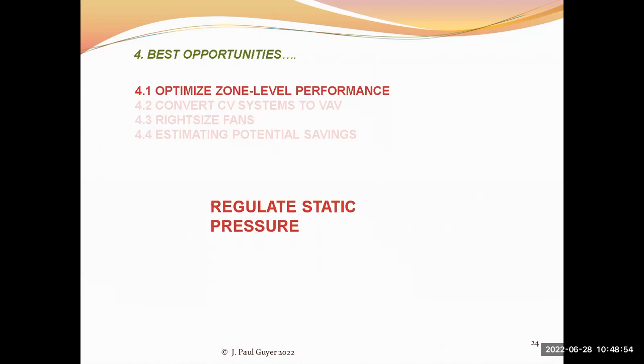In other words, are you forcing air with the fan into the ductwork system at a higher static pressure than is necessary to move the air to the occupied spaces, or are you pushing the air into the ductwork at too high a pressure, and then you're having to throttle it down with dampers as it moves through the distribution system and gets discharged into the spaces.